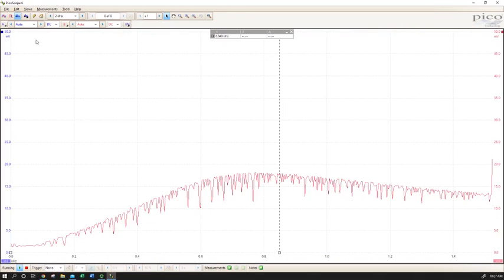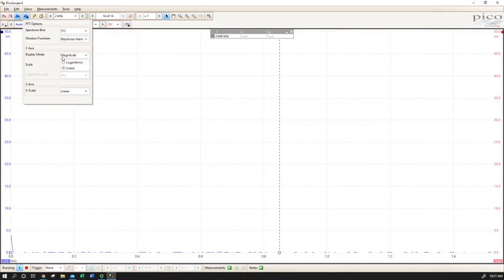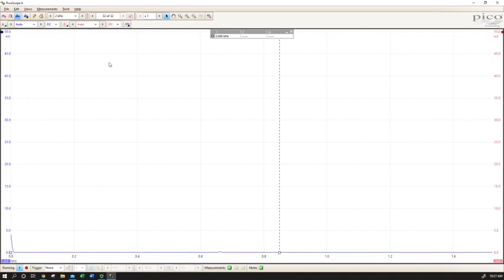So I'm going to go back to my spectrum analyzer. I'm going to click on magnitude to kind of clear it. Go back to peak hold, and it turns out this 512 bins spectral resolution in the Blackman-Harris data collection scheme works really well to show resonance for just about everything that we're going to look at today. So we're going to keep that the same.